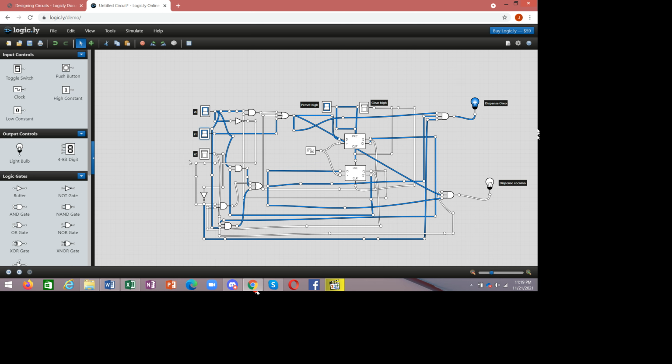I2 is 0, we have not clicked it, so it releases Oreo as per the logic we have discussed. When I turn I2 on, it will automatically switch to Cocomo, because when I2 is equal to 1, meaning when it's glowing blue, we release Cocomo, right? I0 and I1 deal with the money logic, and this one deals with the product logic. So when it's off, it dispenses Oreo. When it's on, it dispenses Cocomo.